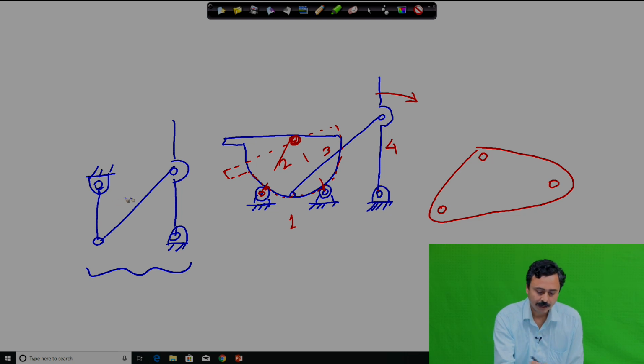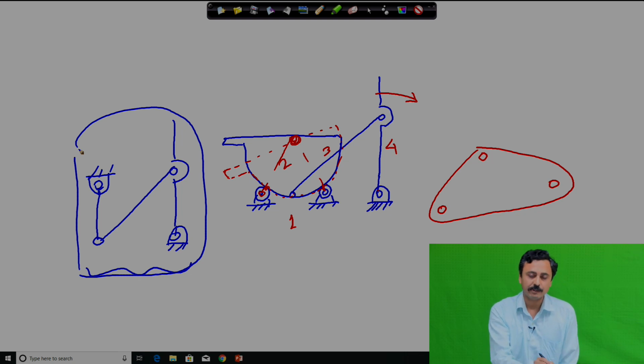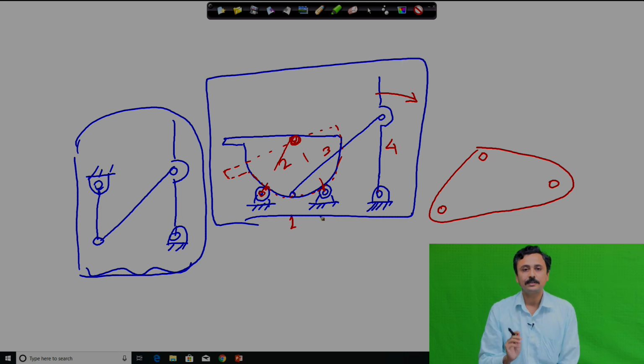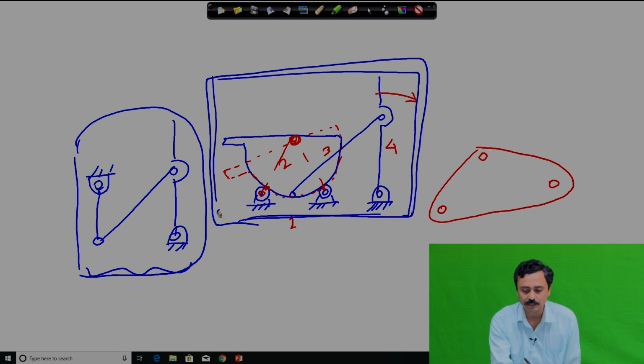So, have we answered this? If you look at the equivalent linkages, then we do not have ternary links, but if you look at the mechanism as such, then we have these 2 ternary links. So, I think if you look at it from these 2 perspectives, then you will understand why we claim that this has these 2 ternary links. Possibly you have looked at the equivalent linkage.